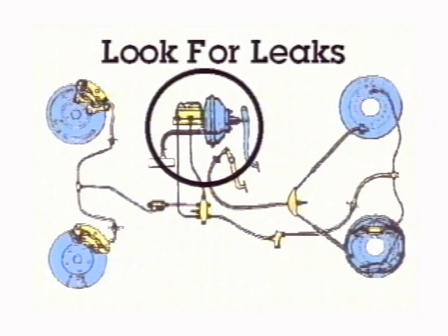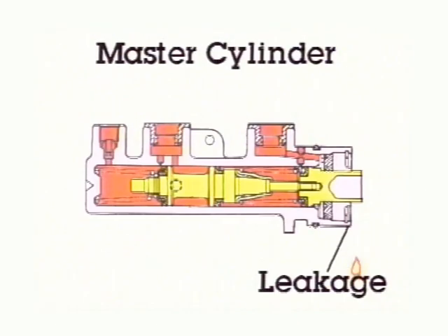Look for leaks behind and underneath the master cylinder. Fluid can leak out of the back of the master cylinder and down the booster or firewall. Rubbing your finger under the bottom rear of the master cylinder will often find a leak.